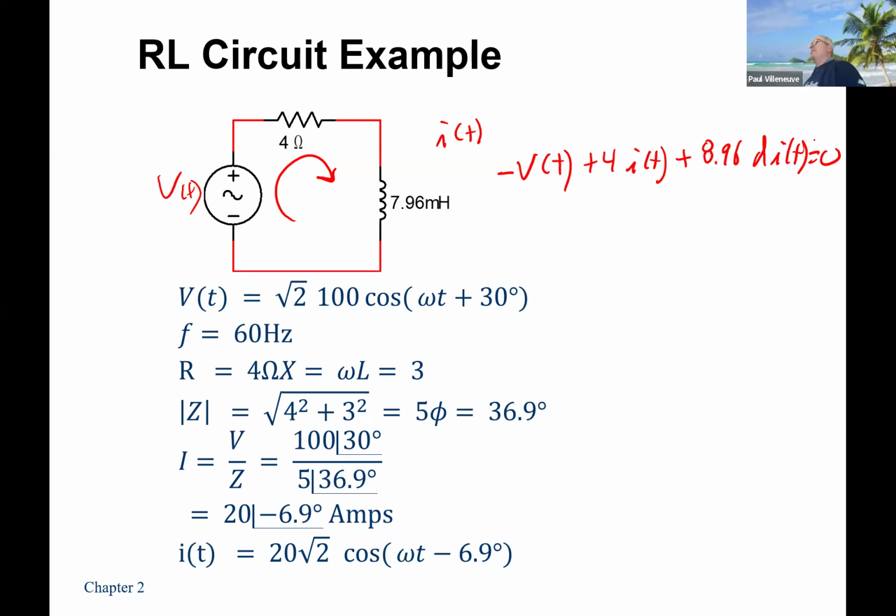You could solve for it, but we actually don't need to do that, because in AC circuits we oftentimes are only looking at things on an aggregate or an average. If you remember, in our second class I showed a diagram of the different time scales. We don't care about things happening in the time domain. In many cases we're really interested in steady state. So we're going to get rid of this and do things with phasor analysis.